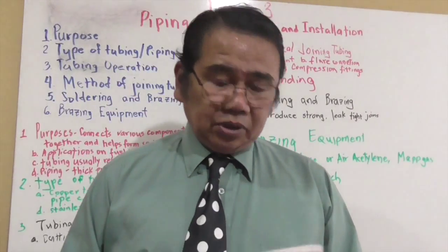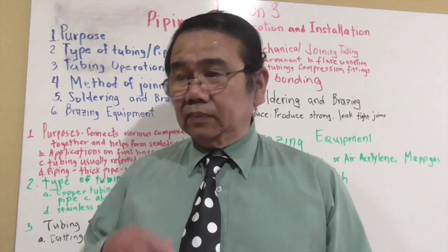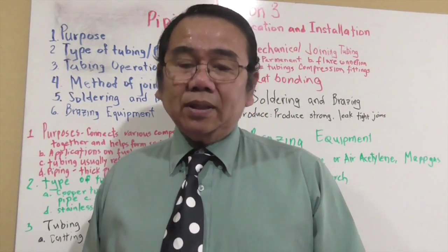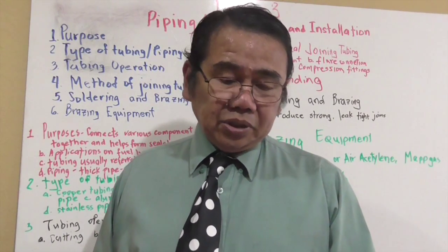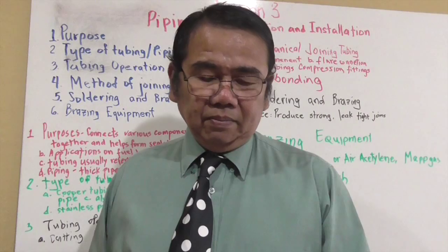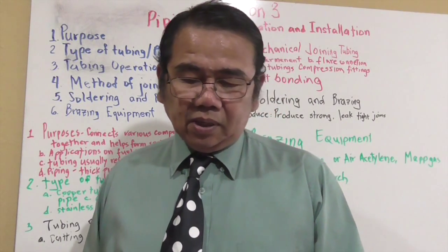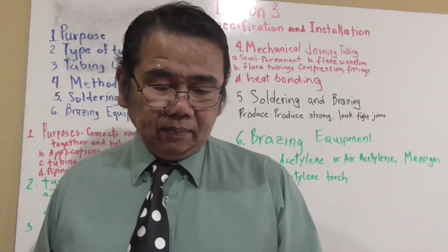Then you gotta talk about safety hints for soldering and brazing. Never attempt to repair a system that is under pressure or vacuum. Many fluxes contain chloride or fluoride.